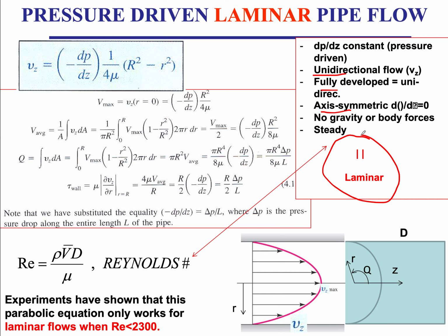So in a laminar type of flow, which is all of the above, the flow is unidirectional, it moves in sheets. So you'll see the flow moves in sheets. It has no mixing between the layers or the laminates. Those assumptions can only happen if my Reynolds number, as we have just defined it before, is less than 2,300. So that's what we call a critical Reynolds number for pipe flow. And when we remain below this number, then it's very likely that our flow is going to be laminar.